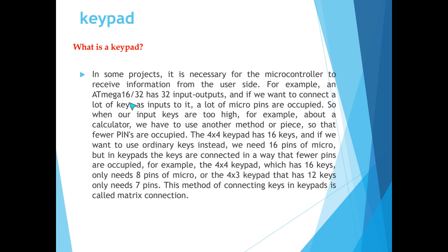Then it includes 32 input-output pins. And if you want to connect a lot of keys as inputs to it, then a lot of microcontroller pins are occupied, and they will be busy. So when our input keys are too many, for example in a calculator, we should use another method so that fewer pins are occupied.